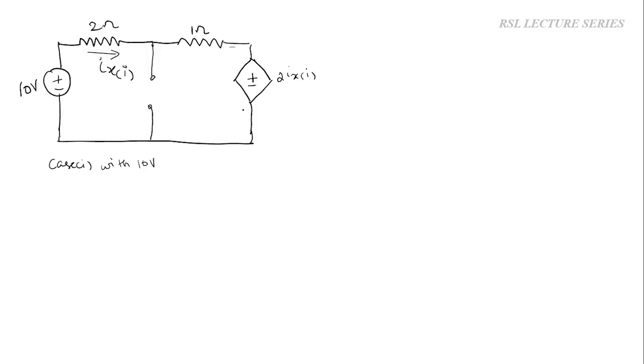So now we have only one loop with 2 sources and 2 resistors. So we will consider one current I flowing in the clockwise direction. Always assume the loop currents in clockwise directions only. So now we have to write down Kirchhoff's voltage law. Here, if you see, the current I is flowing from negative to positive with respect to this voltage source. So this is considered as a voltage rise. If you see this source, the current direction will be downward, that is from positive to negative. So this source is considered as a voltage drop. Next, voltages across the resistors are considered as drops only.